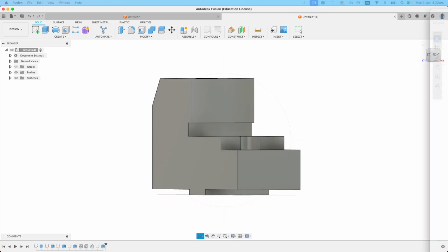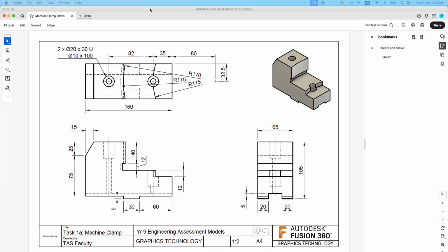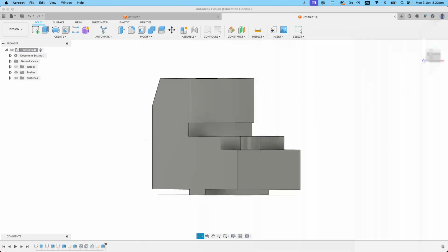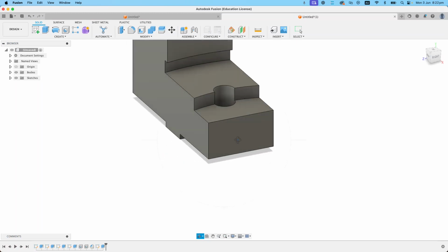All right, let's go back to the drawing. I know I'm going pretty quick here. We can then see there's a little step or a little cut going all the way through. I can see that through the hidden detail here. And we can see here, all right, so what do we got? It's basically 5 millimeters up. It's set in 20 millimeters, even on both sides. That's referenced to that edge there. Okie dokie, back over. So let's do a sketch on this back face.